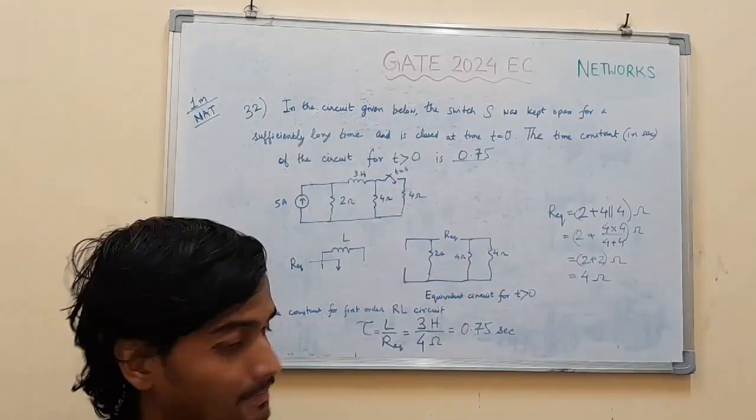Now substituting I1 in terms of V1 and V2 from equation 1, we get I2 in terms of V1 and V2. Finally, we compare both equations with the standard equations, and we get all the Y parameters Y11, Y12, Y21, Y22. Only Y21 was asked in the question, and the value is 1.5 siemens.